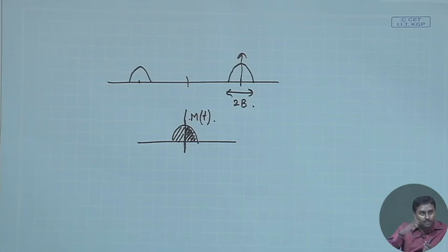It is just because of this modulation that I have suddenly increased it to 2B, and this is just repeating the negative half, which is a mirror image of the positive half. So, it is not required to transmit that. I can always get back my signal, we will discuss that later on, through just one half, either positive or negative. From that portion only I can extract the whole signal. That is possible, we will show that it is possible.